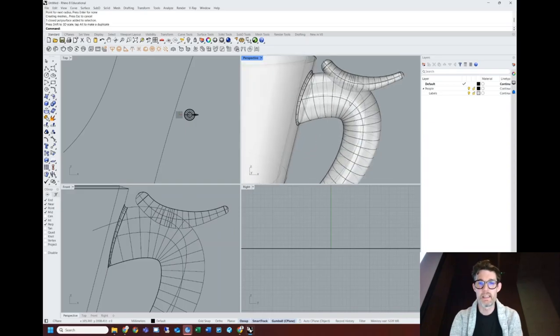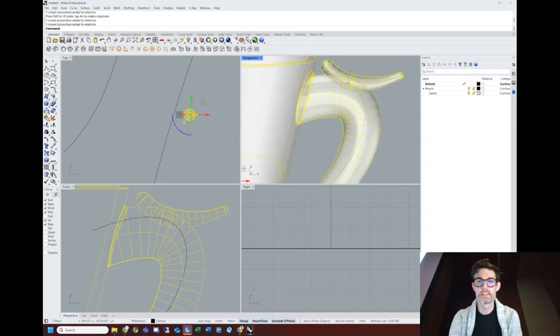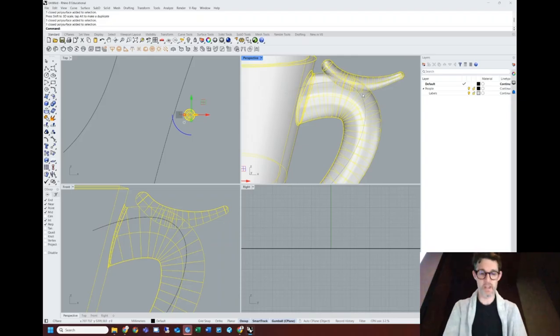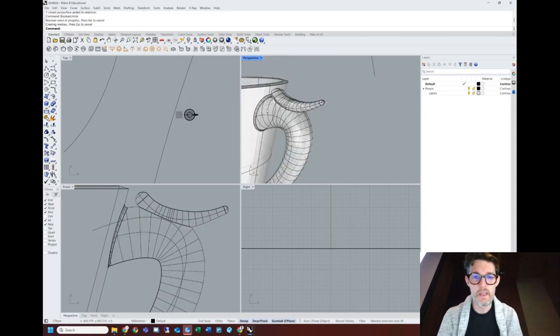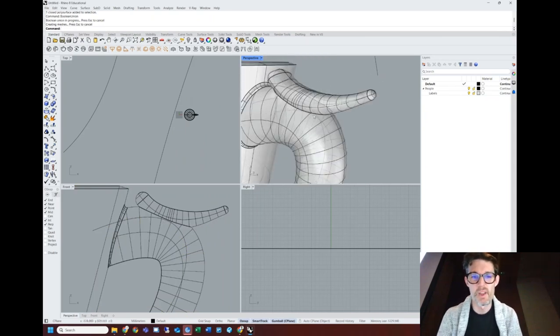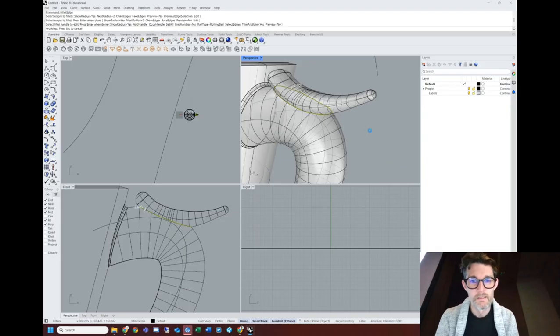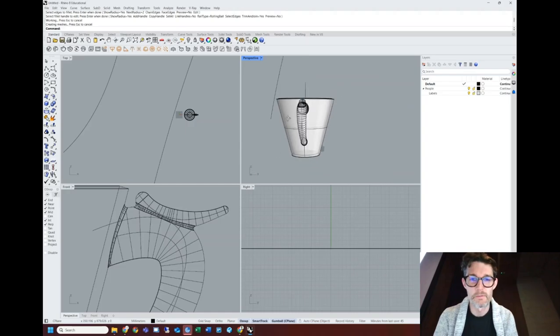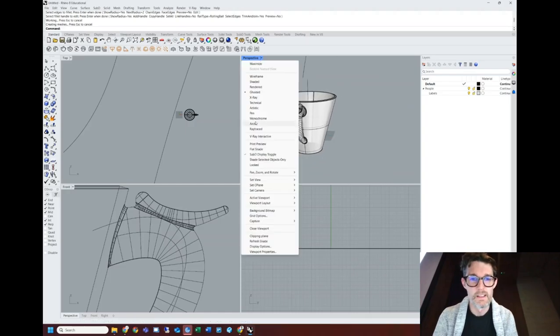And then similarly, I want to make sure that these two things, where they coincide, become just one object. So I'm going to do a Boolean union, and it's going to smush them together. And then I've got this horrible, sharp curve that actually never happens in real life. So I'm going to fillet that edge. And there we go. Now we're looking at something that's kind of got something going for it, right?